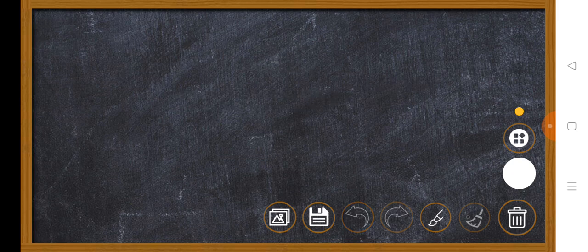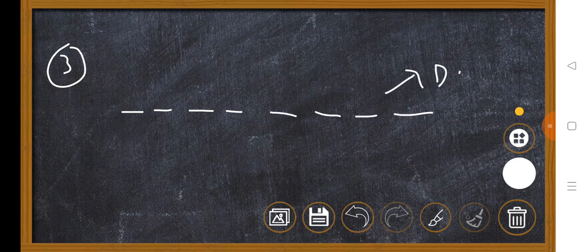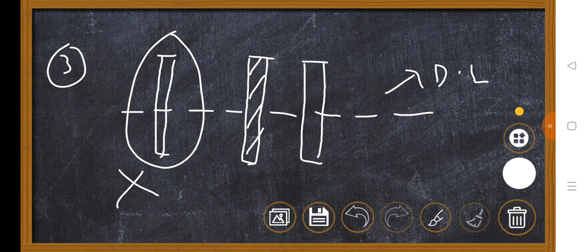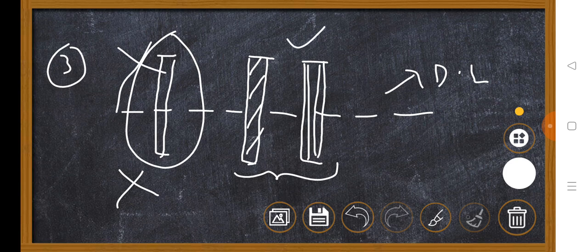And coming to the third rule, you can observe the third rule very easily here. I'm going to show it with a pictorial representation. This is the demarcation line. The third rule in CMOS is that the diffusion should not cross the demarcation line. This is not correct in CMOS, but the poly and metal may cross. This can be allowed in CMOS. Poly and metal may cross, it can be allowed in CMOS. I hope you are clear, all of you. This can be allowed and this can't be allowed. That means the diffusion should not cross the demarcation line.